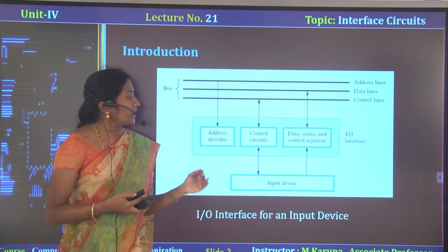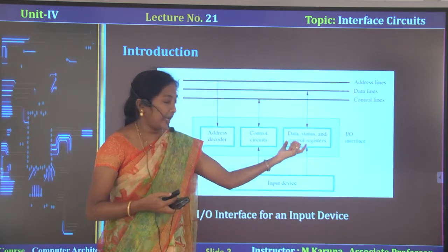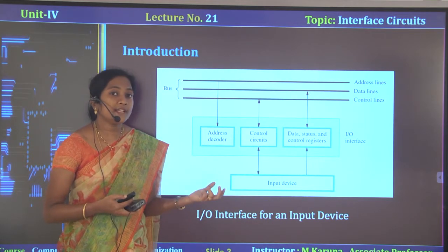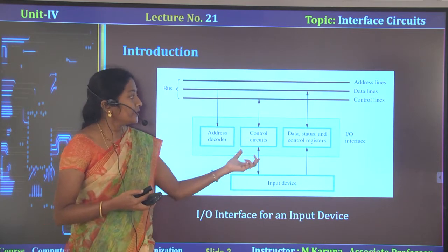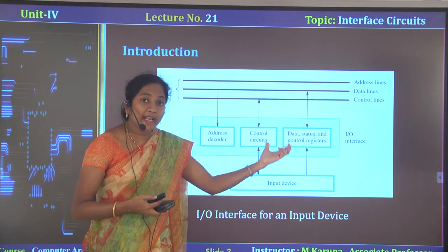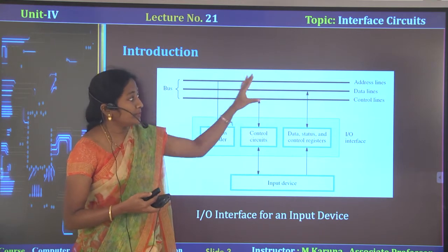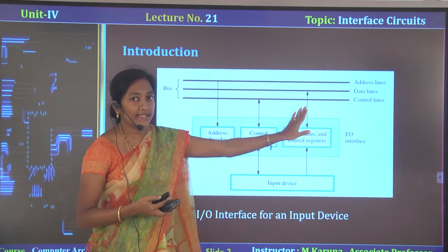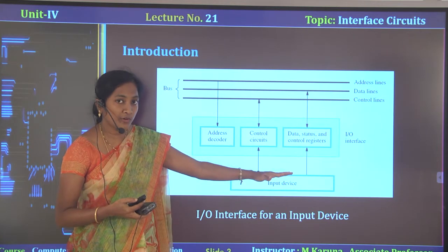Anyway, here all the data registers or buffers are used to store the data, and status registers are used to indicate the status of the data available in the data registers. And this transmission is known as parallel transmission. Here the data is transmitted in parallel because all wires carry all the bits simultaneously. That is why we say this is parallel transmission of data.